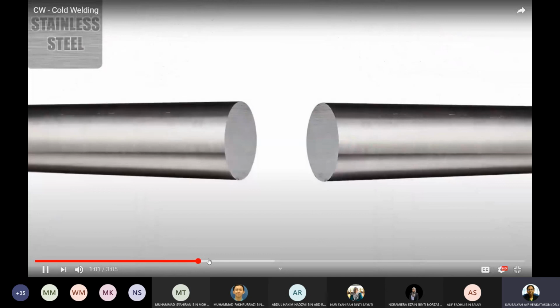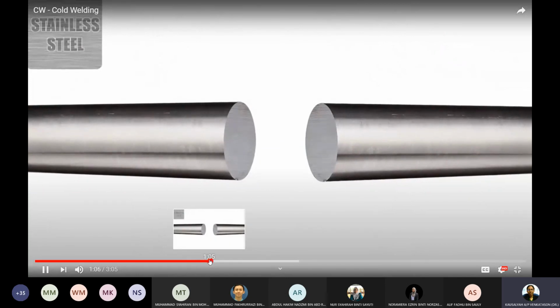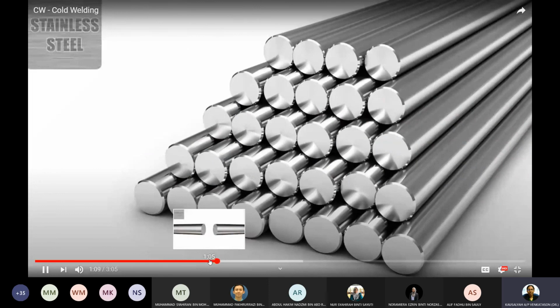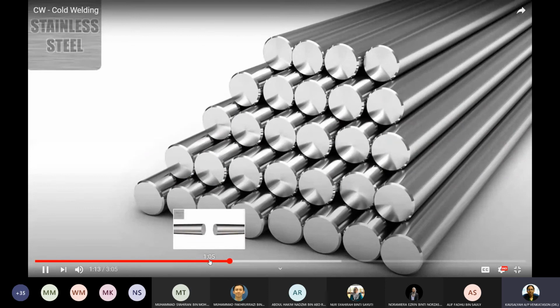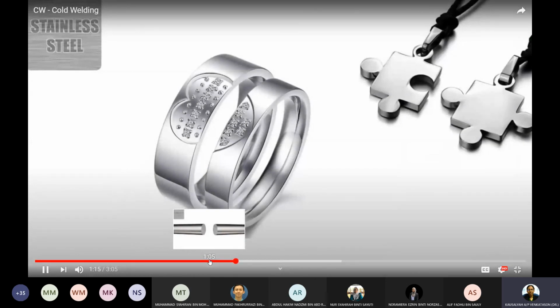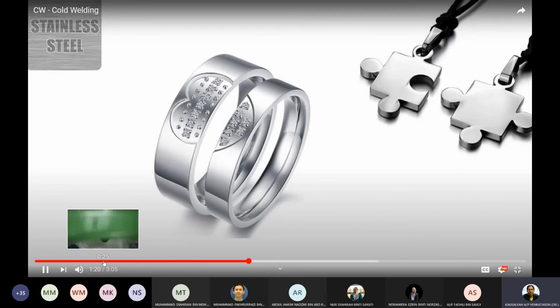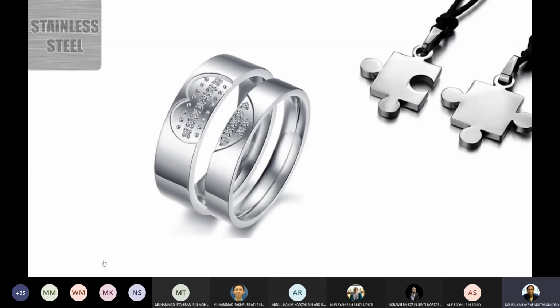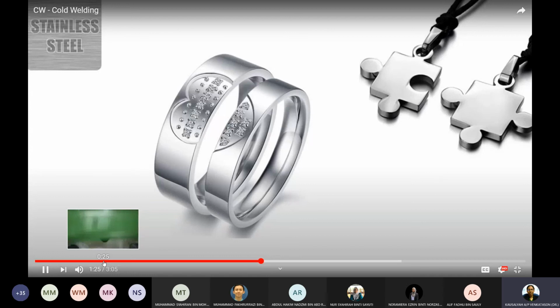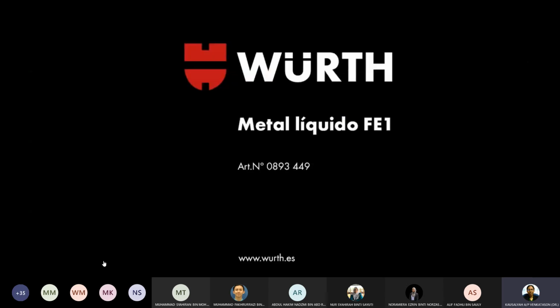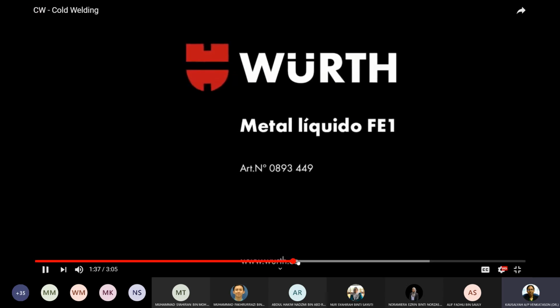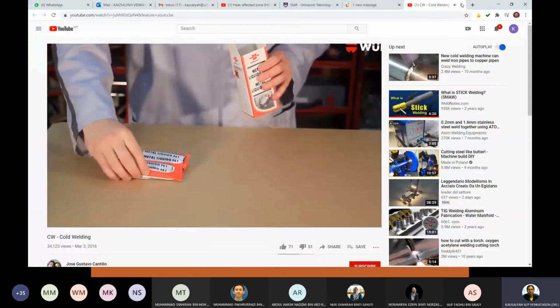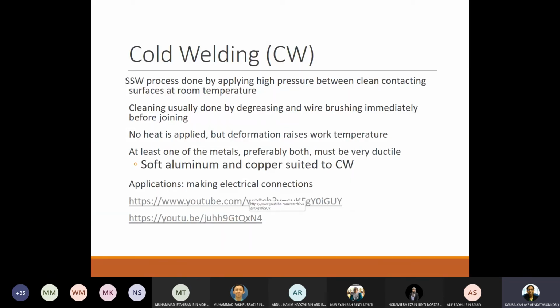You need to get two perfectly smooth corrosion-free surfaces of similar metal, usually stainless steel, and press them together with some force to get them to fuse into one piece, as in the process of cold welding. You need two atomistically smooth surfaces of the same material with the same orientation, uncontaminated by any impurities or surface defects for vacuum fusion to take place. Okay, so that's for cold welding.